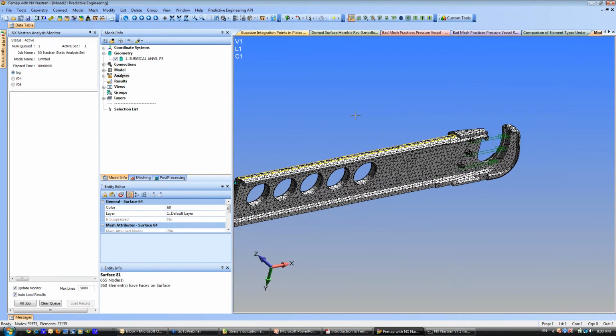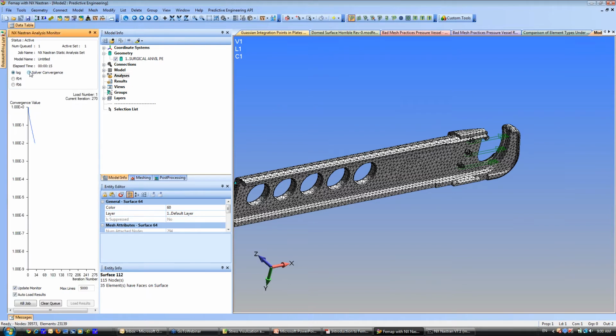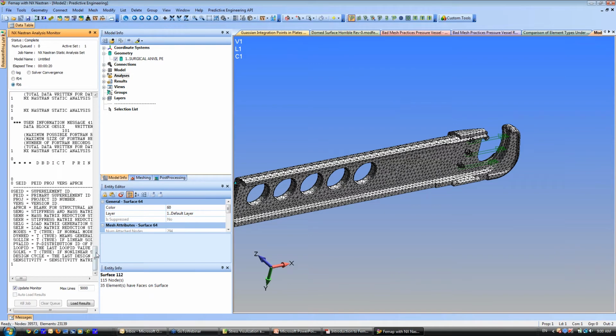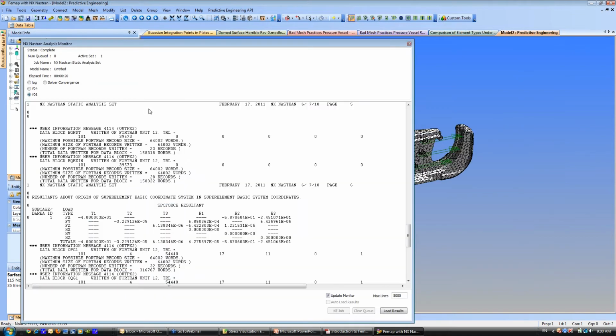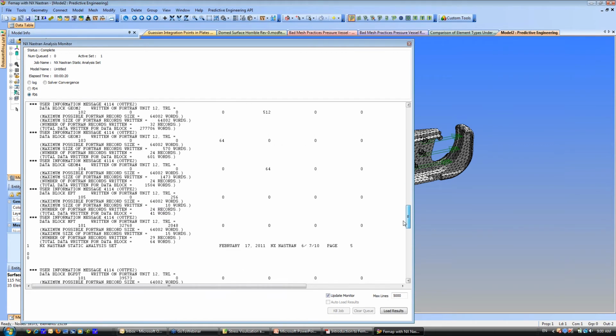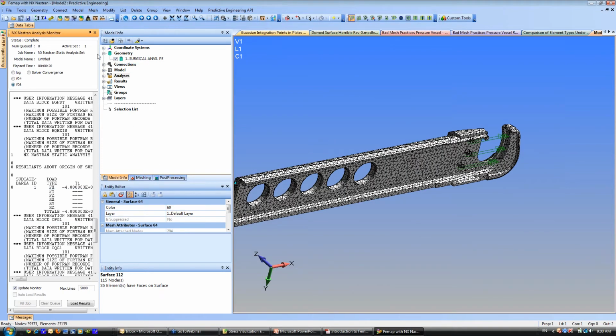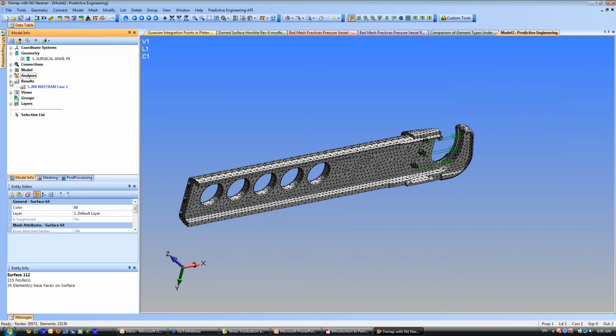These are some of the little details I've covered in the past. And so it fires up. What it's doing is it'll write out the nodes and elements into a Nastran deck. I'm going to turn the selector off. It writes it out as a Nastran deck, then fires up the Nastran solver, and it's going through the solver convergence. And it's done. You can go through here, and one of the things I always recommend is look at the load going in, 40 pounds. SPC force, load going out, 40 pounds. Looks good. Okay. We do have a result set.